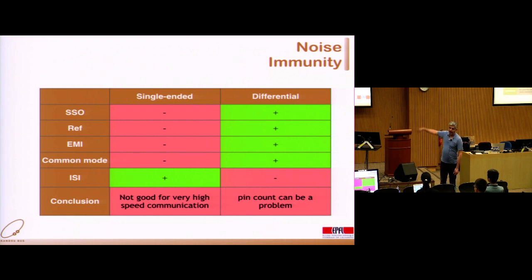Within a column, I have the same frequency, so the conditions of noise are more or less the same, at least within the rows in a column. In two different columns, the frequencies are different, so the noises are different. For example, when you use differential, you have to go at twice the frequency to get the same throughput per wire. That's why the intersignal interference is worse.